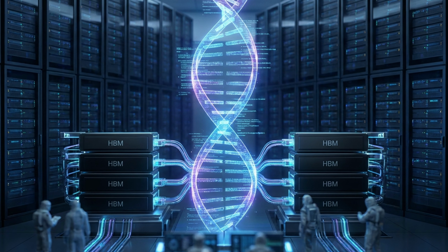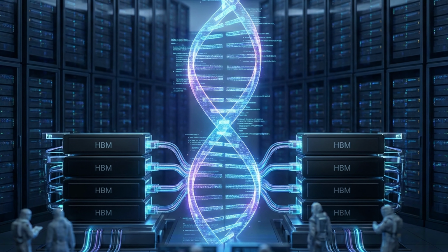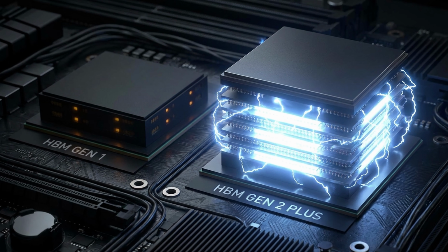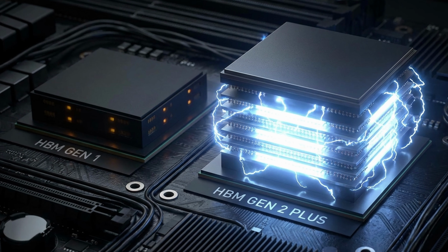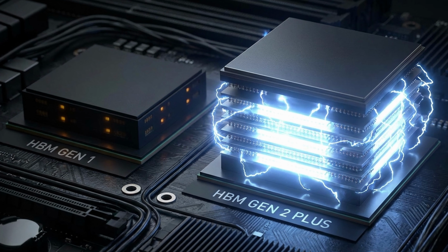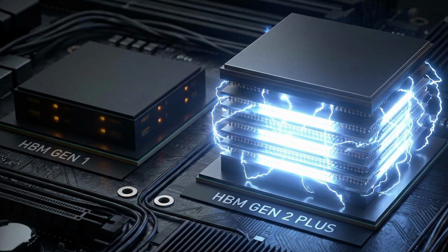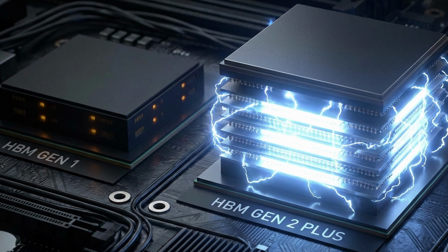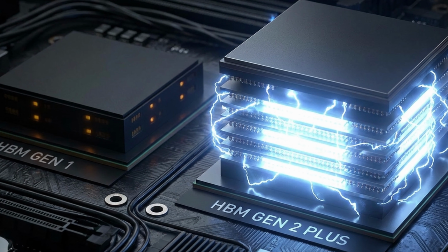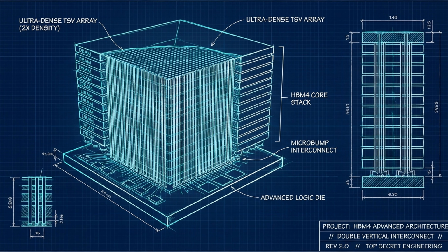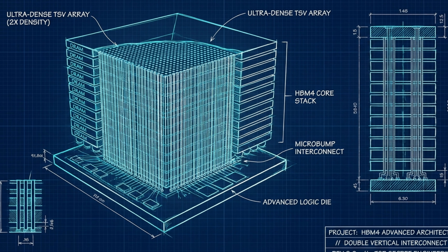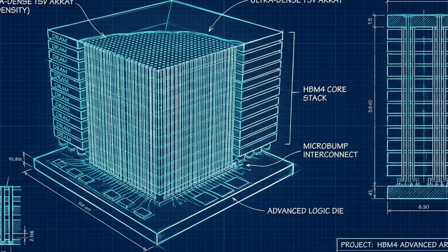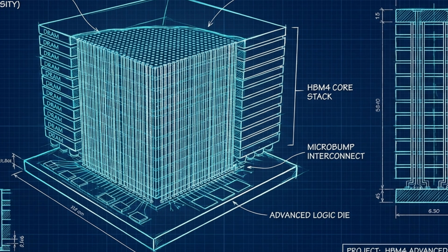The progression of this memory technology has desperately tried to keep pace with the scale of language models. While the previous generation featured 80 gigabytes of capacity, yielding roughly 3.3 terabytes per second of bandwidth, the newest architectures integrate 192 gigabytes, capable of pushing an astonishing 8 terabytes of data per second. Future iterations project doubling the interface width yet again, to ensure that incredibly high parameter models and long context inference engines are not choked by memory constraints.